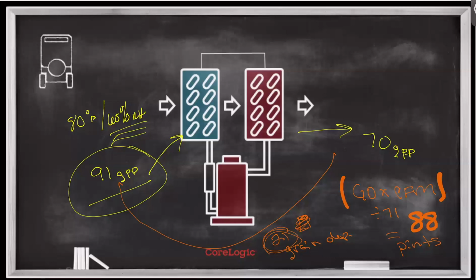So I'll say it one last time, mark it down somewhere, try it out and use it: grain depression times CFM divided by 71. And the beauty of this math is that this math for humidity control, and understanding the actual amount of humidity control from a system, isn't just unique to a dehumidifier, right?